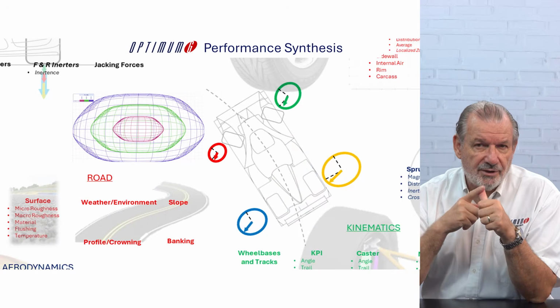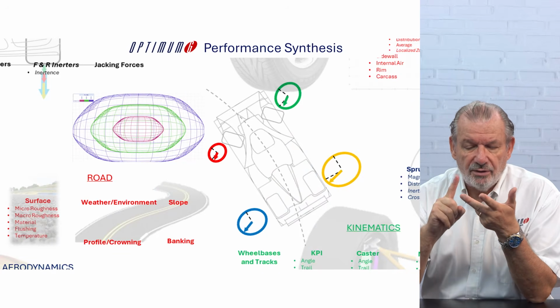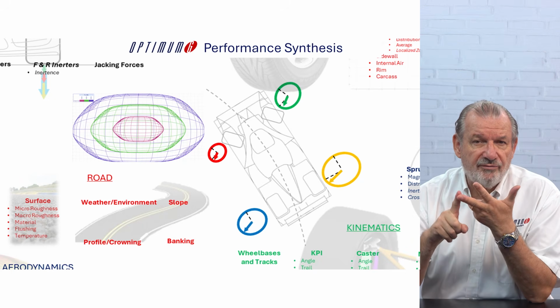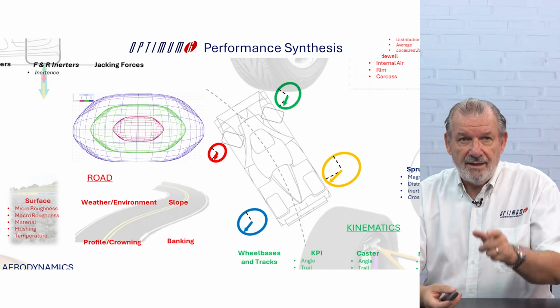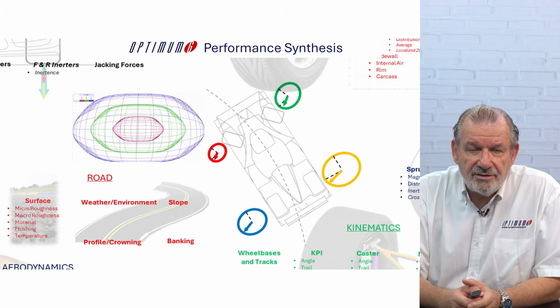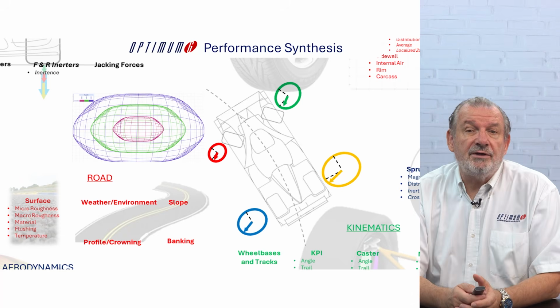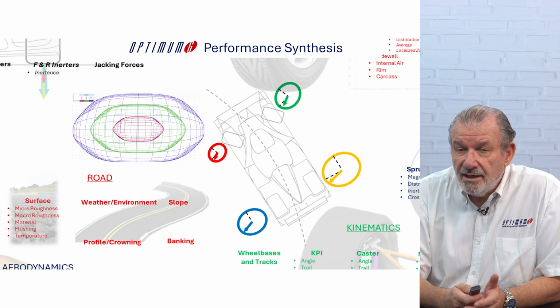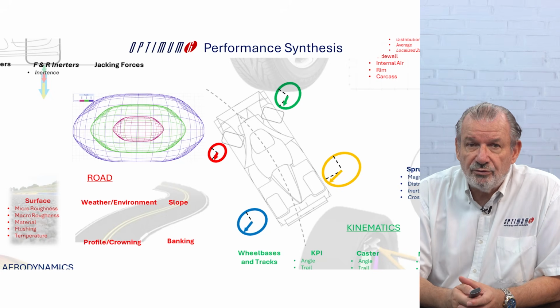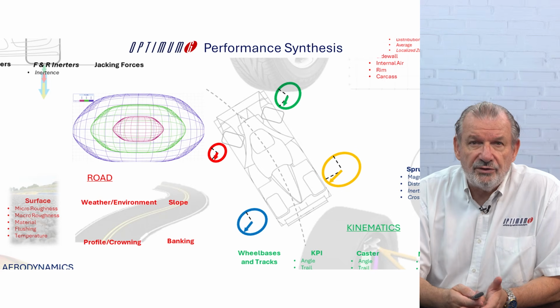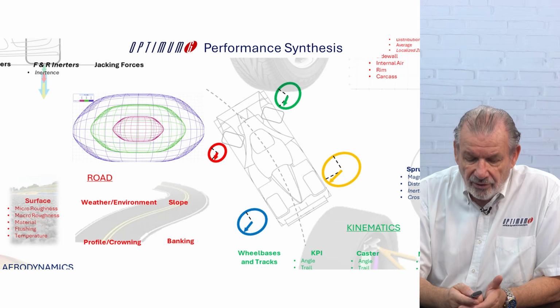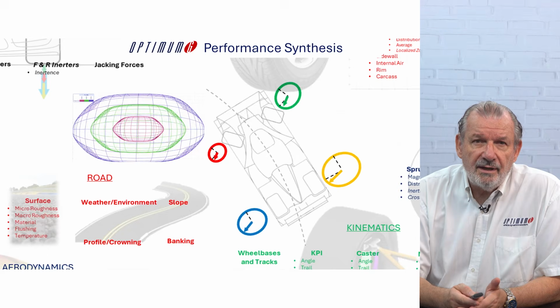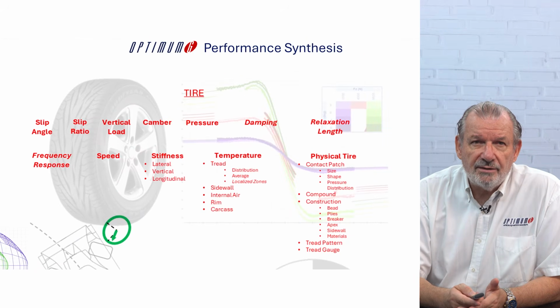An FX for braking and acceleration, an FY lateral, a self-aligning torque, multiplied by four, you have 12 causes of the yaw moment. This, ladies and gentlemen, is the beginning of vehicle dynamics. That's the alpha and omega. That's the beginning and the end of the OptimumG seminar also, because what we do is start to understand the puzzle of everything.